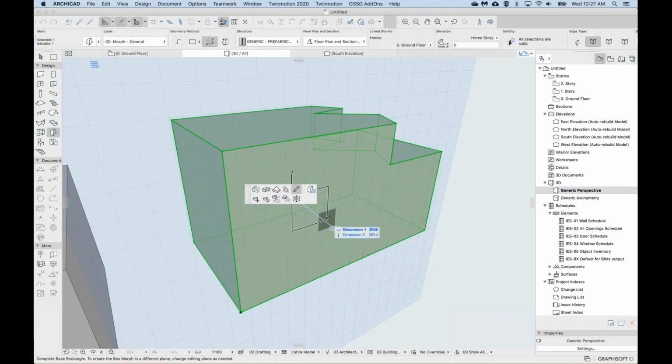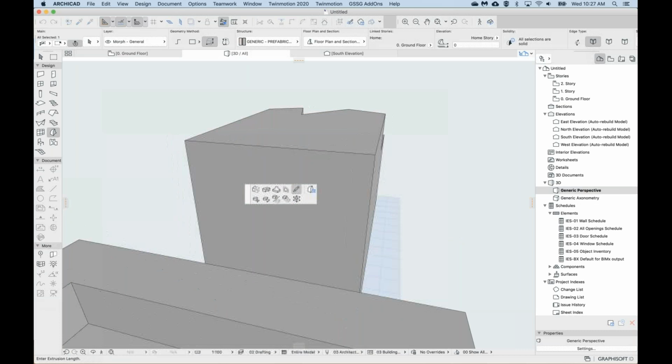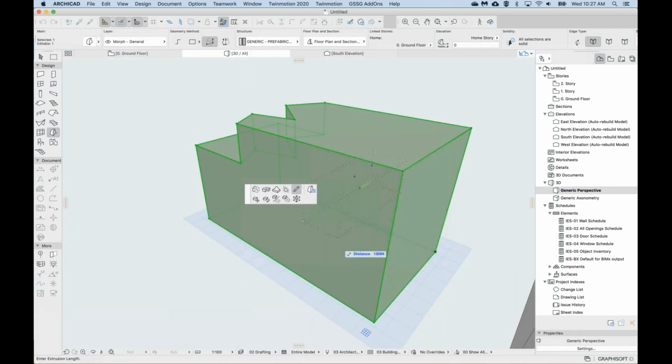So maybe I'll show it and then do it a couple of times. On the surface, I'm clicking the pencil, so instead of an edge, choosing the box method. With the box method, I just need 3 clicks. I just need a diagonal to get the rectangle. And now I need to push this box to the other side.